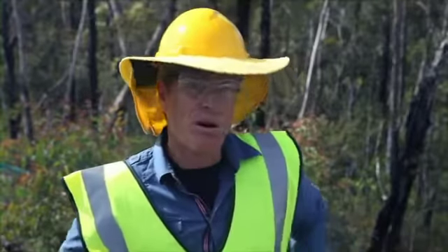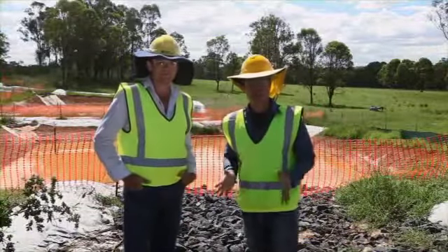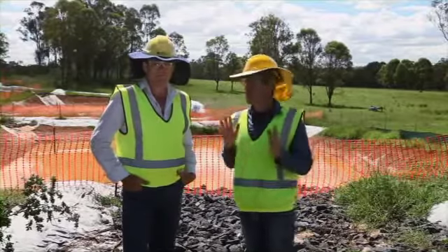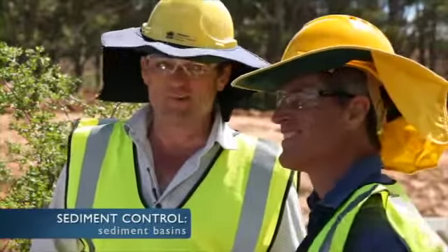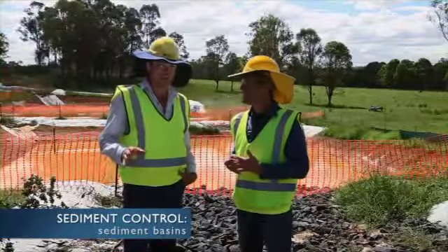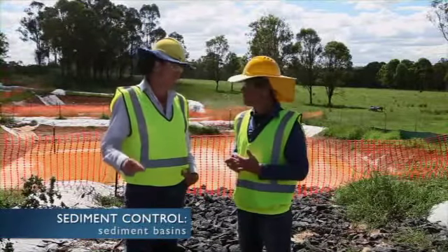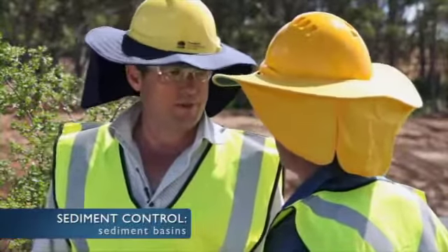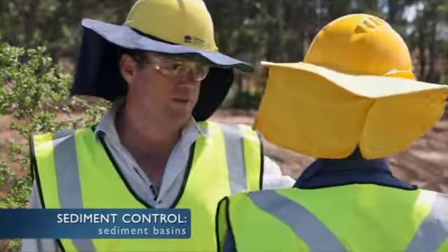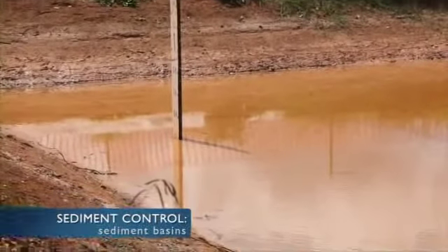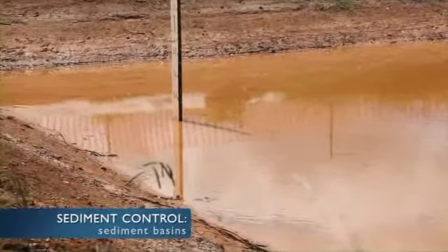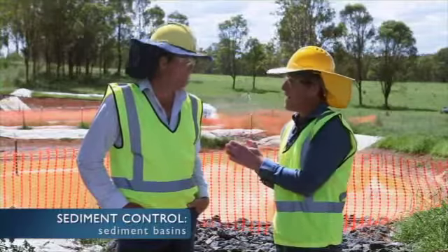Now let's have a look at one of the really effective ways. Let's have a look at the big guns of sediment control, and Chris, they're sediment basins. Yes, Pete. Sediment basins are our most effective way to control large volumes of sediment-laden runoff on the construction site. Sediment basins, or sumps, on smaller sites are essentially holding reservoirs, which will allow the water to sit and allow the sediment to settle out before the water is discharged to the receiving environment. Question from left field though, are they static?